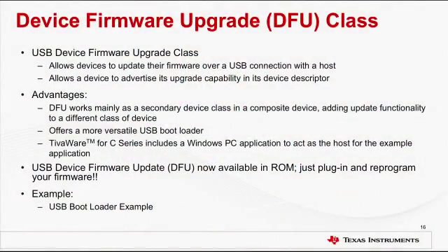Many predefined functions exist in the USB HID class. These functions allow hardware manufacturers to design a product to the USB HID class specification and expect it to work with any software that also meets these specifications. One of the other most commonly used USB classes is the USB Device Firmware Upgrade class. It is an official USB device classification of the USB Implementers Forum. It specifies a vendor and a device-independent way of updating the firmware of the USB device.